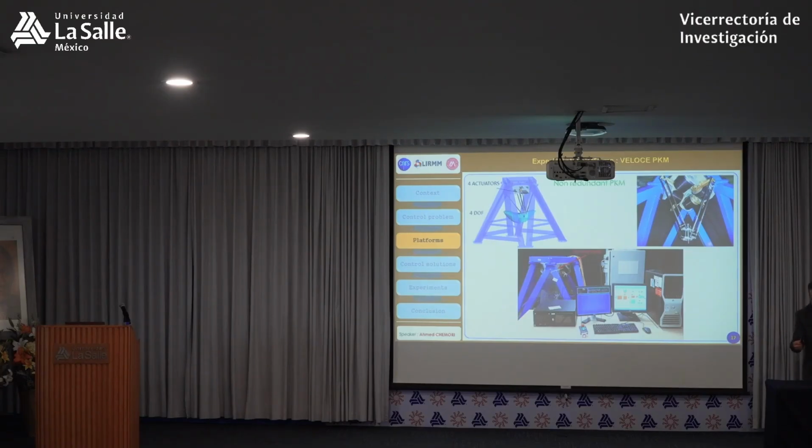And the weight of this one and this one is not the same, and the inertia is not the same. So in this case, we need a robust controller. And in the robust controller, or the adaptive controller, we can estimate the mass of the object in real time. This is what we did. We designed a controller. When we take the object, we estimate the mass and the inertia, and we can compensate in the controller. So this is why adaptive.